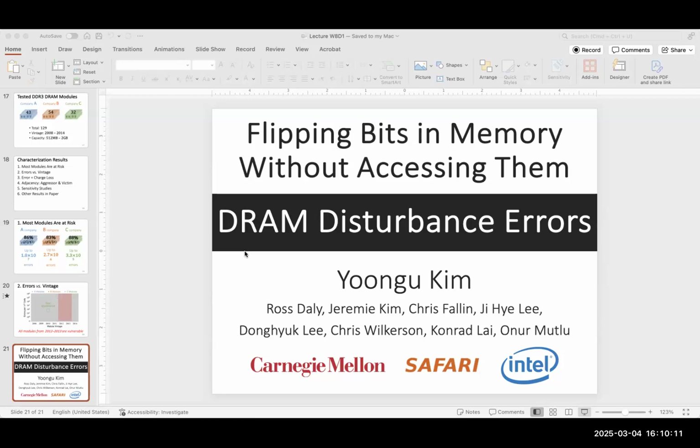Your question is correct, but your reason for having dynamic noise margin is not correct. Your hypothesis or your question, is there a situation where we can have a dynamic noise margin? Yes, not for resource consumption, but actually to conserve power. There are systems which do dynamic voltage scaling, DVS.